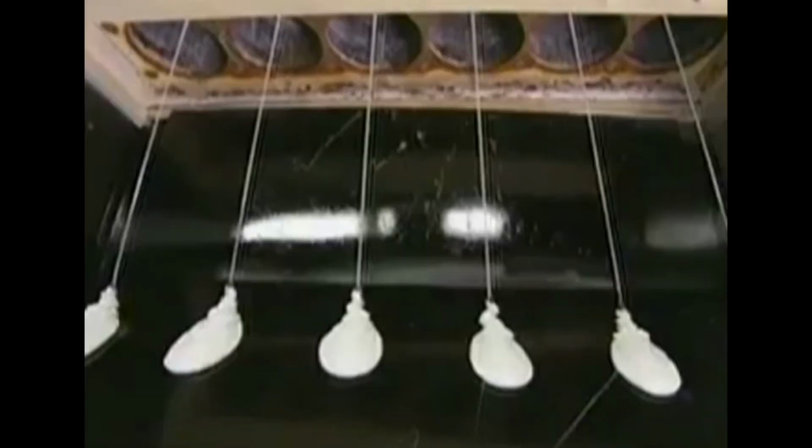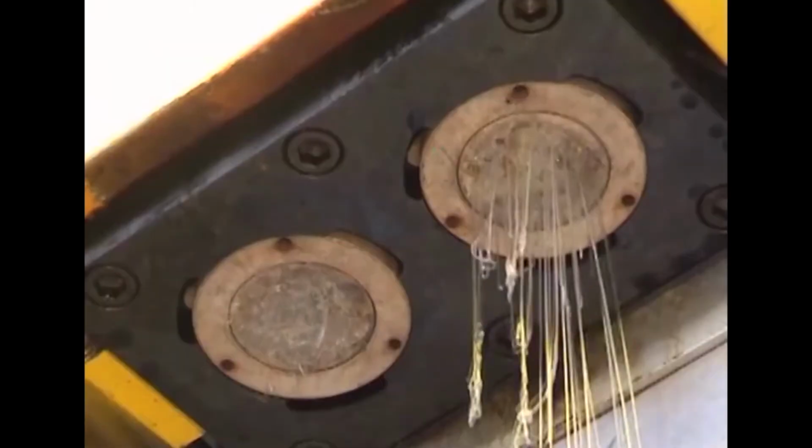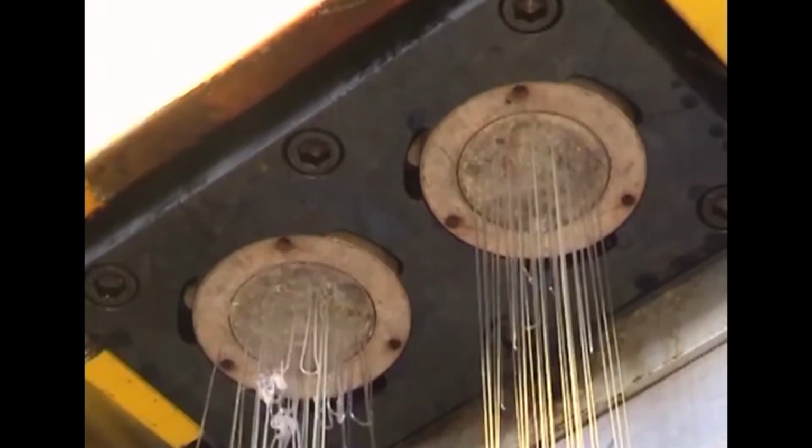And so, it is first filtered to remove all the suspended particles and then vacuum treated. If it contains a small air bubble, that also will interfere with the formation of longer and continuous filaments. And so, it is vacuum treated to remove the air bubbles, and then it is stored in the storage tanks. From the storage tank, the molten solution, that is a free flowing polymer, is made to pass through the holes of the spinneret.